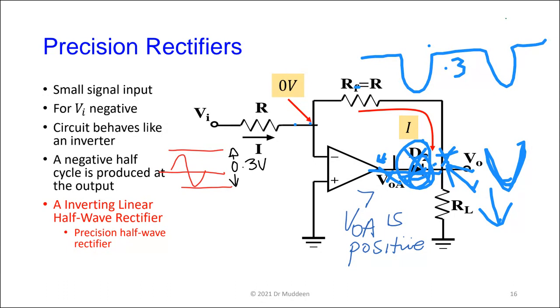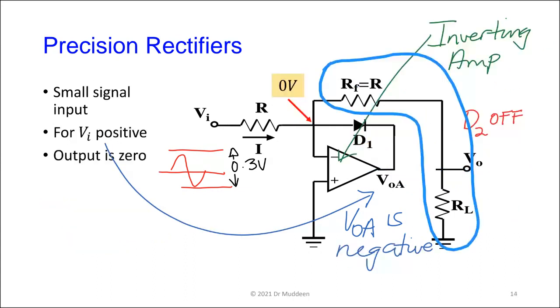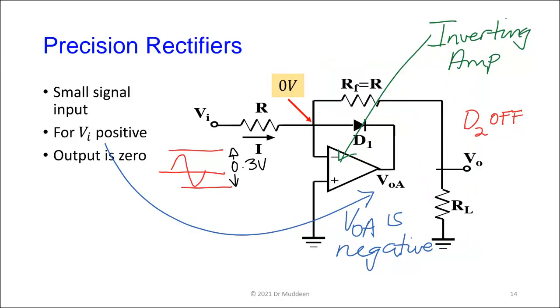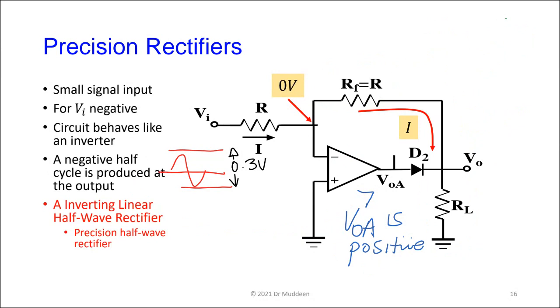So you could put in that and you could get, right, so the purpose is to switch the output, to connect the amplifier to the output. This is what I was saying. So depending on what happens, when one diode is off, the output of the op amp is disconnected from the output of the circuit. And when the other diode is off, the amplifier works in its normal way. Yeah? That's the only purpose.